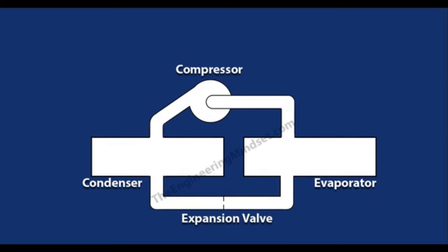Now, there are three main circuits in a chiller which you also need to know about, so write this down as well. We've got the refrigeration circuit, the refrigeration loop, and this is the refrigerant which passes around each of the four components and transfers that heat from the evaporator over to the condenser and back again, a constant loop, getting the heat out of the building and over to the condenser where it can be sent to the cooling towers.